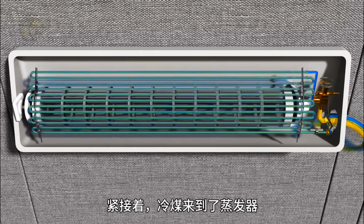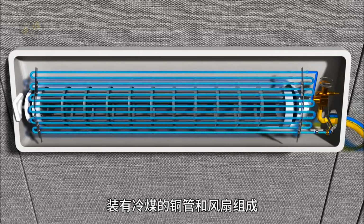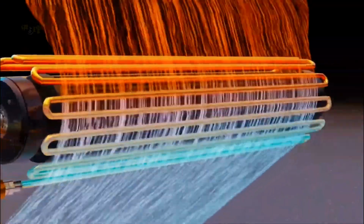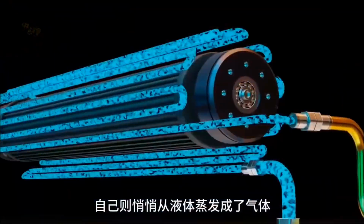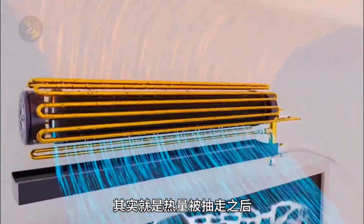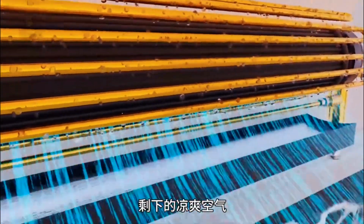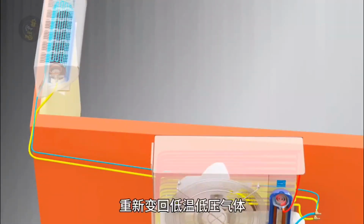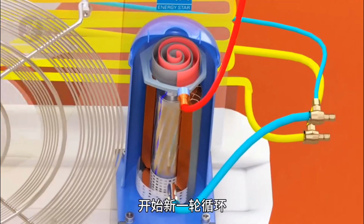Next, the refrigerant reaches the evaporator, which is also composed of a row of densely packed copper tubes filled with refrigerant and a fan. The fan blows indoor air over the evaporator, and the refrigerant begins to absorb the heat from the air, quietly evaporating from a liquid into a gas. The cool air you feel is actually the refreshing air left after the heat's been extracted. At this point, the refrigerant's temperature remains around 5 to 10 degrees Celsius, reverting to a low-temperature, low-pressure gas. Then it is sent back to the compressor to start a new cycle.